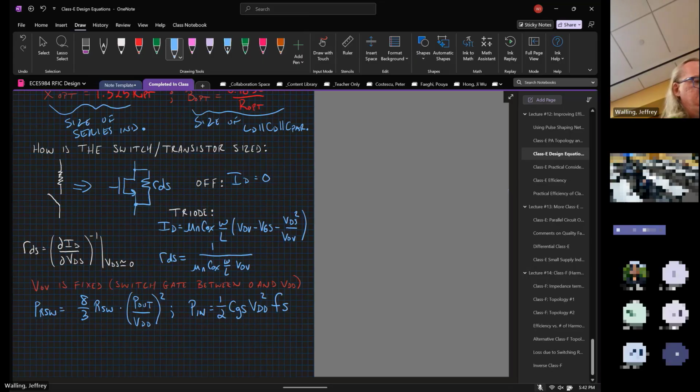And what we see fairly immediately from this is the switching resistance comes from the drain to source resistance formula. Oh, sorry, the input power they call switching losses. So again, if you're talking about power electronics, they talk about balancing your conduction losses and your switching losses. Switching losses are due to switching some capacitance. Conduction losses are due to ohmic losses from resistance.